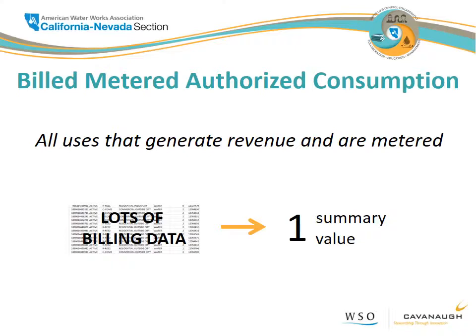There are no duplicate records, for example, that you haven't mistakenly included non-potable water, so there's no raw water distribution in there, there's no recycled water accounts in there. It requires that you've made sure to clean away any financial adjustments that don't have to do with volumes exchanged, because we're really interested in the volume here, and sometimes our billing processes can muddy a little bit of that pure volume determination.